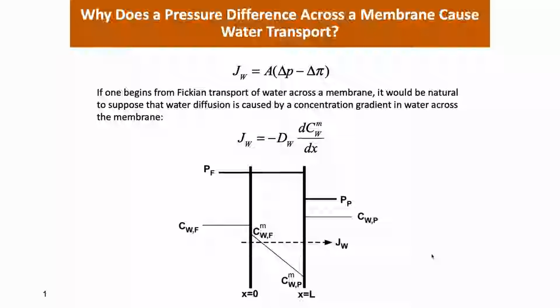It assumes that the materials are non-porous and that the way that water, salt, organics, other small molecules partition and transport through polymers is according to the laws of thermodynamics for the partitioning, and Fick's law of diffusion for transport.